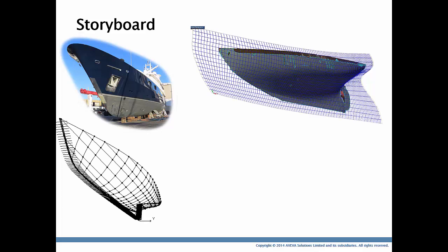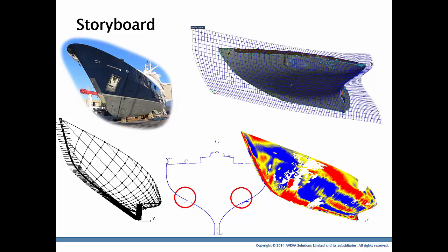We'll then start looking at my own solution, which is very much a curve-based solution, generating a surface from a set of curves, and some of the challenges involved in turning the laser point cloud into a hull surface definition. And then looking at the validation process to make sure that the surface you're generating is actually the one that you wanted to get and it's accurate to the laser survey scan.